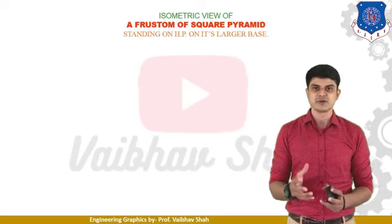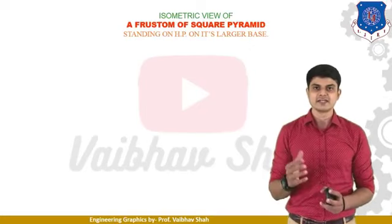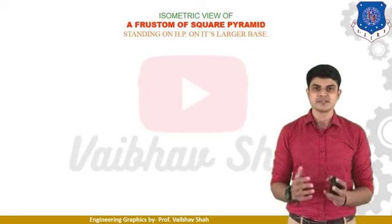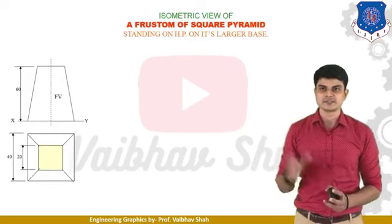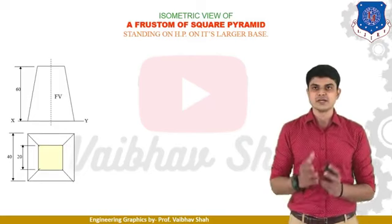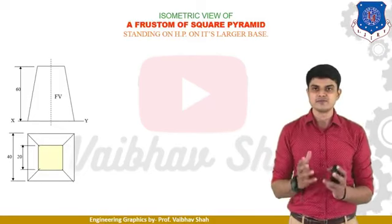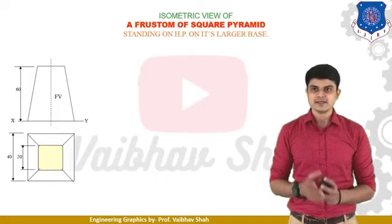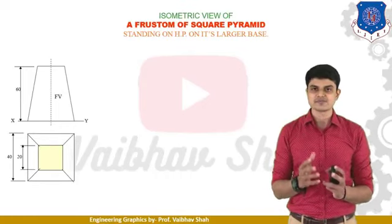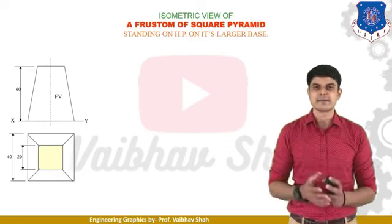That means we first need to draw the square. And then for the frustum, we need to cut this square pyramid. So let us see how to draw this object. This is a view of your frustum of the square pyramid, in which your bottom would be a square and also your top would look like a square. We have the dimension of the square as 40 mm for the bottom and 20 mm at the top.